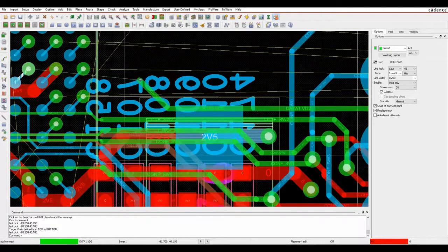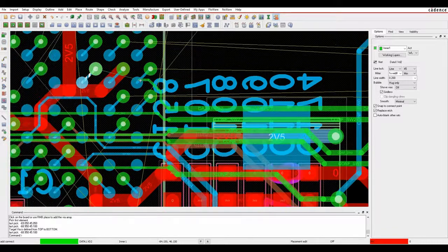So obviously I've got quite a thick default track thickness. When I go into the BGA area, I'm never going to be able to fan out this BGA correctly or escape this BGA correctly based on this track thickness, so I can use something called a constraint region or rules by area. You can see as soon as I enter the BGA, the track automatically necks down to the thickness and to the spacing between the 2 traces to allow me to meet the constraints that I need to get